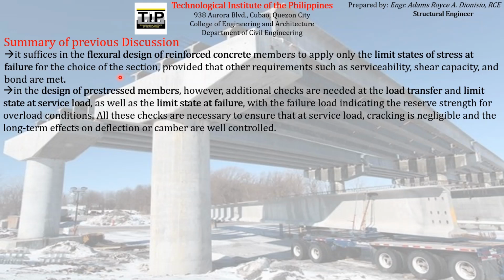But for the case of pre-stressed concrete members, when we design pre-stressed concrete members, we don't just check the limit state at failure. We don't just check what particular section can withstand the ultimate loads that will be expected to be supported by the member that we are designing. But we also do additional checks, which are the checks of the stress at the load transfer and at limit state at service load.